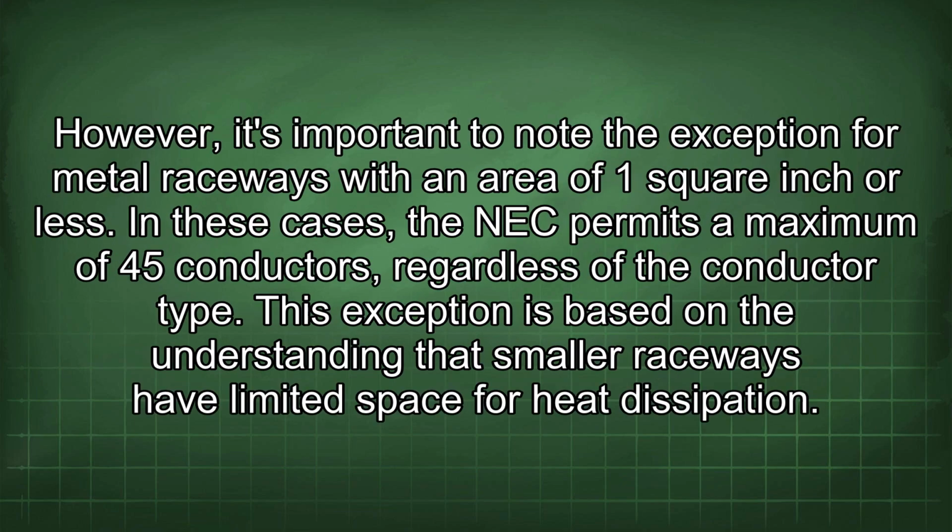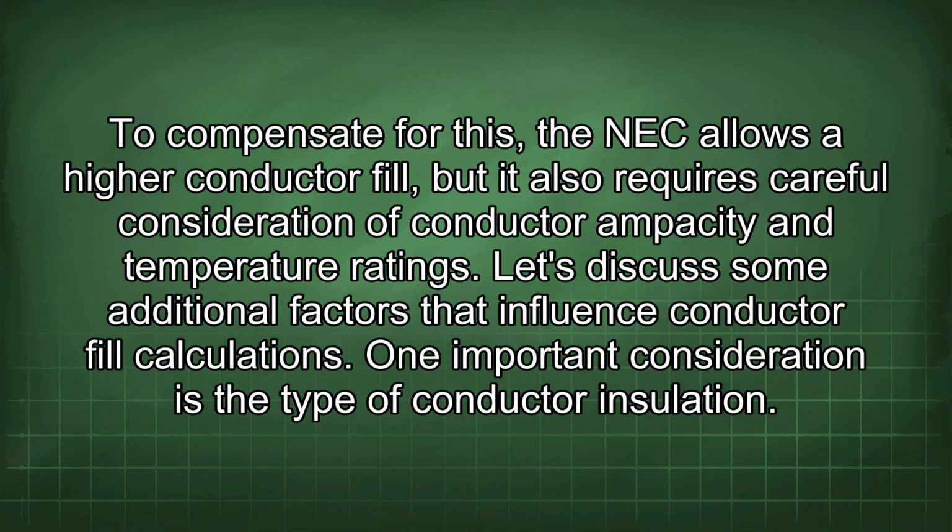However, it's important to note the exception for metal raceways with an area of 1 square inch or less. In these cases, the NEC permits a maximum of 45 conductors, regardless of the conductor type. This exception is based on the understanding that smaller raceways have limited space for heat dissipation. To compensate for this, the NEC allows a higher conductor fill, but it also requires careful consideration of conductor ampacity and temperature ratings.